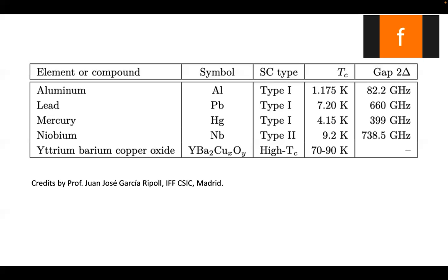Okay, this is one example. Why people don't use those high temperature superconductors for building superconducting circuits, for building quantum bits, is because of the difficulty of fabricating chips. Unfortunately, you cannot really use those lithographic techniques for drawing nice circuits using those, because all those materials are ceramics, essentially.